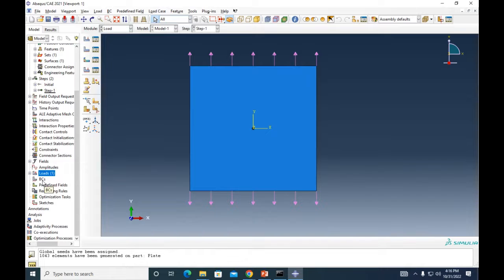Boundary conditions. We have to fix. So if some of you are doing stresses or this type of analysis and you're getting errors, probably the reason why is because of this: we have to fix some nodes in here in order for Abaqus to give us a solution.